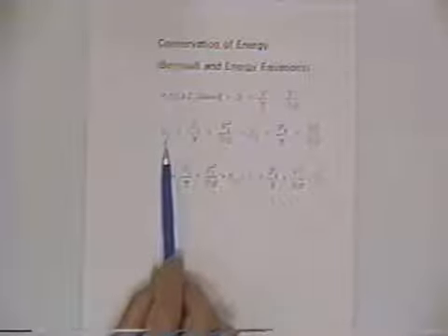And if we write Bernoulli's equation for an ideal fluid without frictional resistance or head losses, we're just saying the elevation head at one location plus the pressure head, same location, plus the velocity head at that location are equal to the summation of the same terms at another location, in a channel, in a pipe, or whatever. But in reality, in a non-ideal fluid, you have frictional resistance and head losses. As the hydraulic energy is converted to heat energy and dissipated to the environment, and so we have a head loss term. So we've got the total energy upstream is equal to the total energy downstream plus the head loss that occurs between the 2 points.